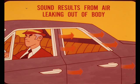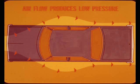In many cases, the sound results from air leaking out of the car body. You see, when the doors and windows are closed and cowl vents open, forward motion of the car pressurizes the car interior with ram air. Besides, airflow around the car body produces low pressure outside the door glass on both sides of the car, especially in the front pillar area.